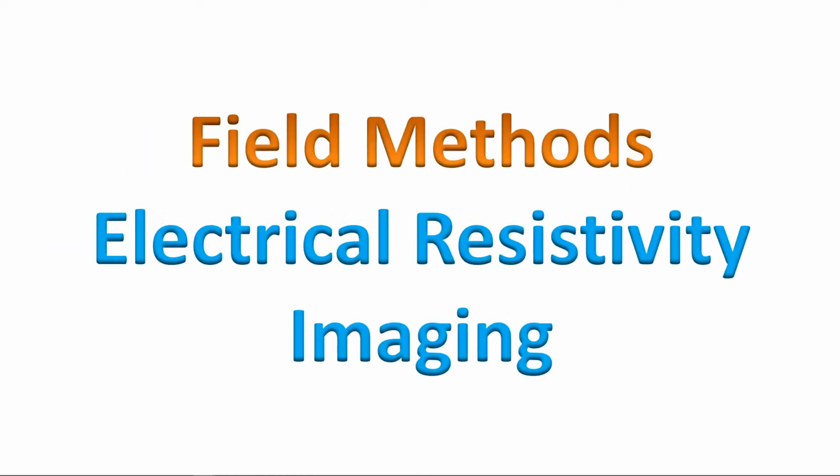I did this, for example, when I was doing field work in Ireland. We did electrical resistivity because we wanted to drill two monitoring boreholes, and we used electrical resistivity to identify where to drill them. In Ireland it's a karst system similar to here in Florida, but here in Florida the karst is kind of fluffy and wet. In Ireland, it is hard and dry.